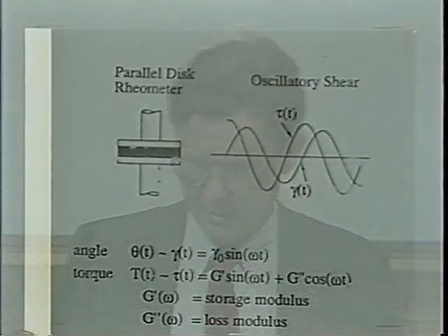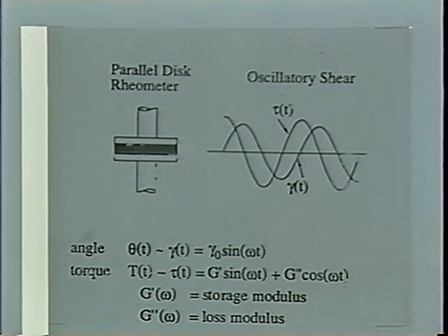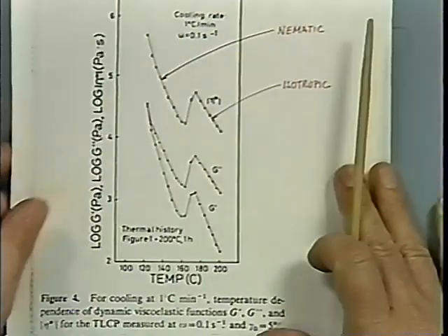She used the dynamic mechanical test, as discussed before. The duration of this period is the probing time, which corresponds with the size of the relaxing unit. We have very large units because of the texture in the Vectra material. Therefore, we have to go to very low frequency and see what the behavior is. All experiments have been done in the nematic state.